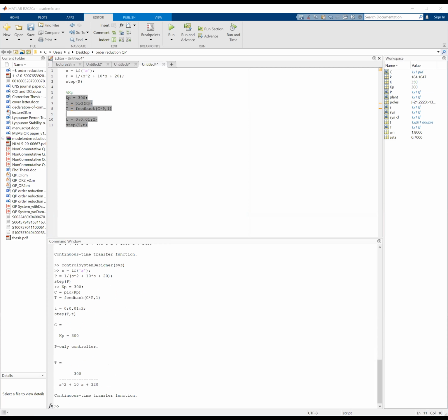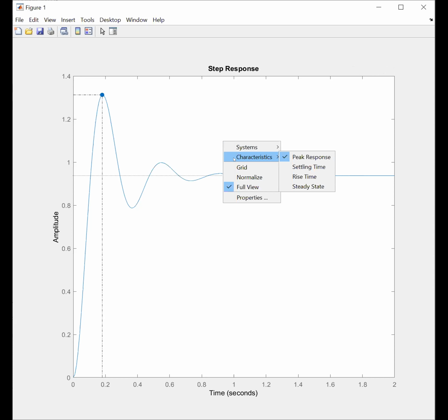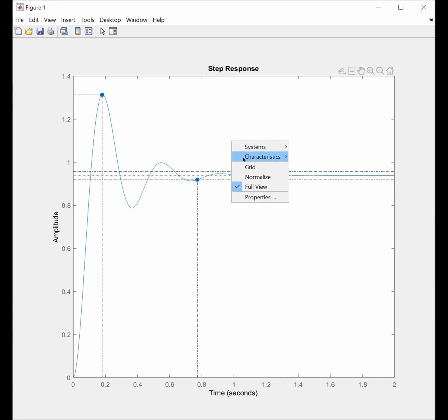and then I want you to see how my response looks. Can you see my step response now got sort of oscillatory and bounded? Initially it was not like this. And again, now I'm meeting the initial specifications. Here, I can select peak time, settling time, and rise time.